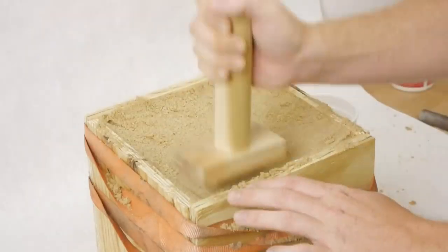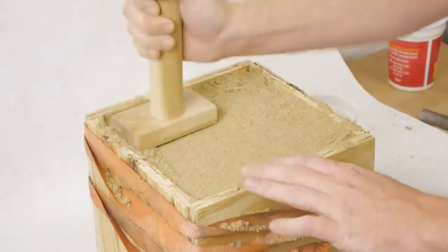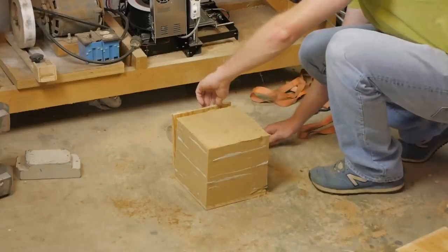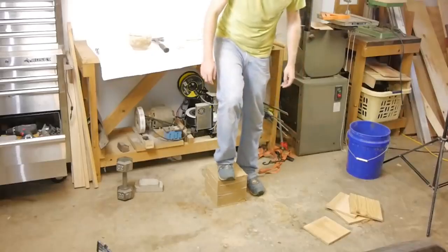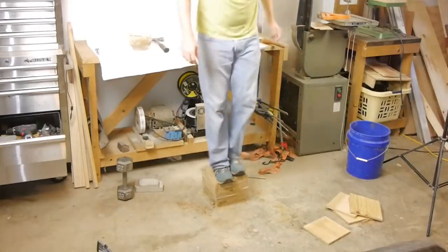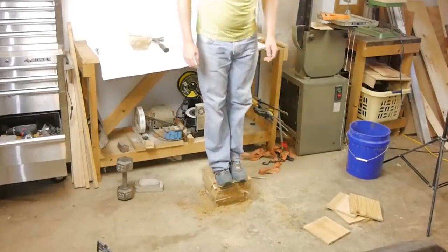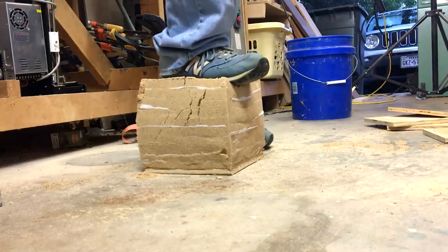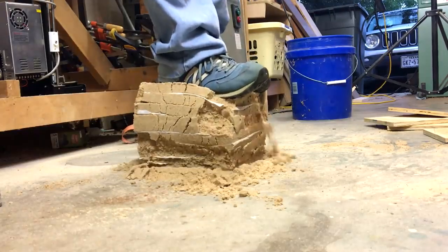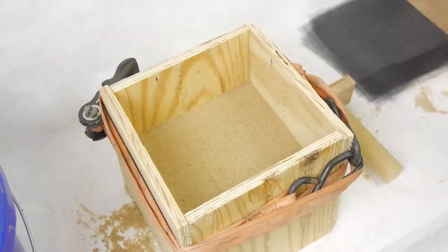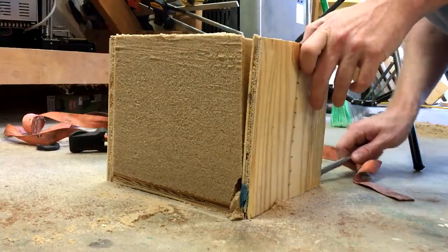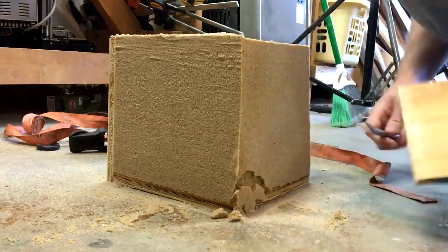This part is not to demonstrate the strength of MSE, but rather to show that the soil really is transferring load into the reinforcement. The t-shirt material is stretchy, so when the vertical load is transferred into the reinforcement, it spreads out and deforms. I wanted to demonstrate this because it may not be obvious in the next example. For the next test, I use pieces of fiberglass window screen as reinforcement. This is a much stiffer material that doesn't deform under load.